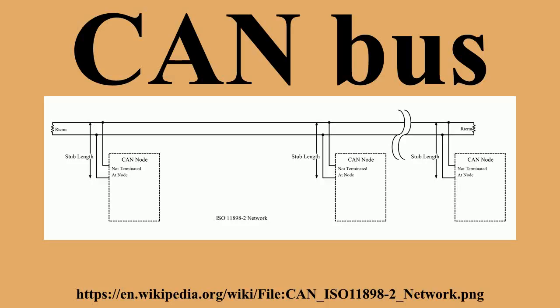Electric park brakes. The hill hold functionality takes input from the car's tilt sensor and the road speed sensors via the CAN bus to determine if the car is stopped on an incline. Similarly, inputs from seat belt sensors are fed from the CAN to determine if the seat belts are fastened, so that the parking brake will automatically release upon moving off.